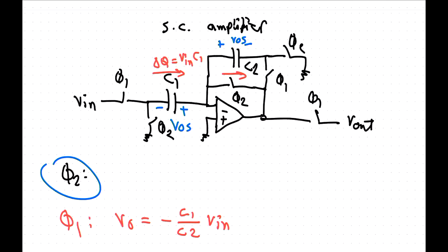You sample the input voltages, then you get an output voltage. You sample what you have at the input of your op-amp, which is the offset plus the gain error that you have. You sample that on a capacitor, and then you do it again. And you could keep going and really get, I don't know, infinite gain if you have infinite time. You're sort of just driving down that gain error. Yeah, you can. Okay.